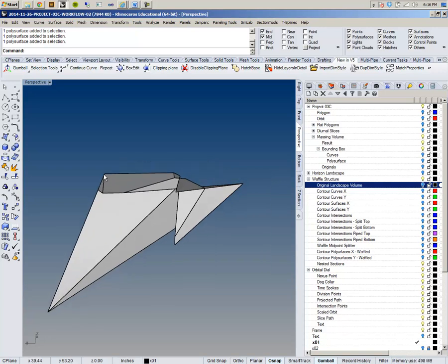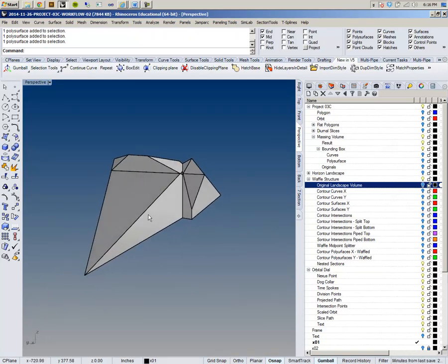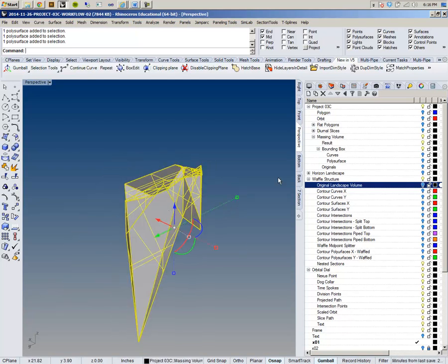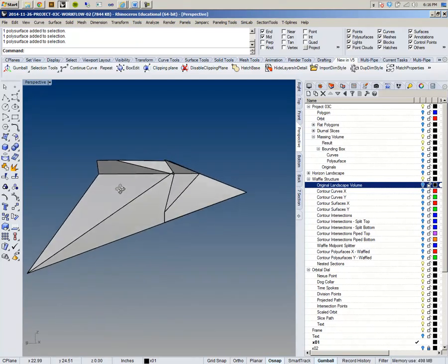It's not going to be very accurate right now because it's going to create a bounding box around the whole thing and give me the center of the bounding box, and that's going to seem kind of random. When I did it for this one, for instance, it goes down on this edge somewhere. It's not even close to the real middle because it's taking into account this whole object. But if you run this command on one of them, it works pretty well. And for me, I'm treating this as my main one in the center here, right?